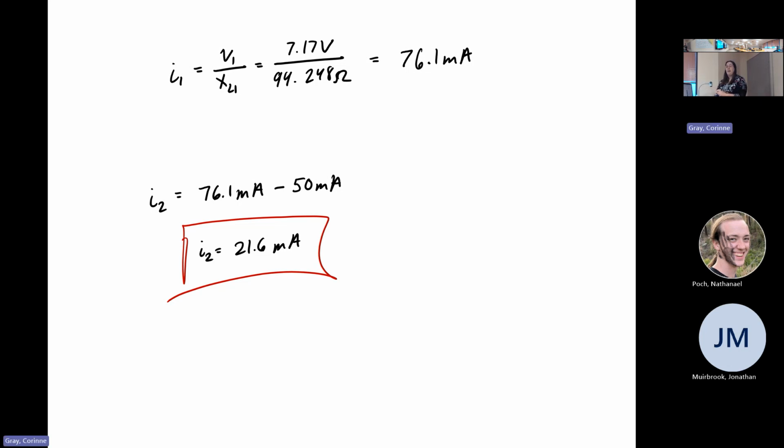So again, anytime that we have an AC source, even if it's capacitors or inductors, there's a really good chance you're calculating the reactance value. So convert what you can into reactance. Then we can treat everything the same way we did with resistors. That's using current dividers, voltage dividers, superposition, all that fun stuff comes back when we put it all into reactance.